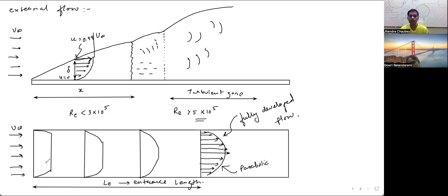So there will always be some span of the pipe which will not be considered as part of the heat transfer. The heat transfer properties are always calculated beyond this fully developed region. So this was about the boundary layer and the fully developed flow in the pipe. I hope you understood. In this case, the Re would be less than 2000. After fully developed? Yes, after fully developed.